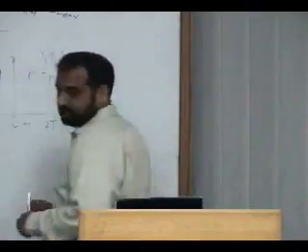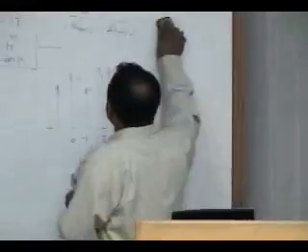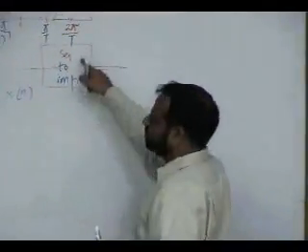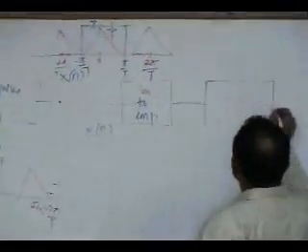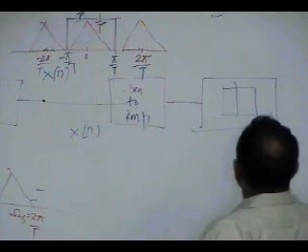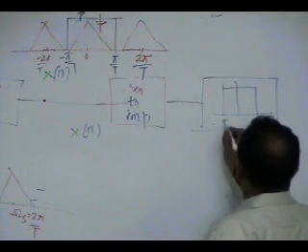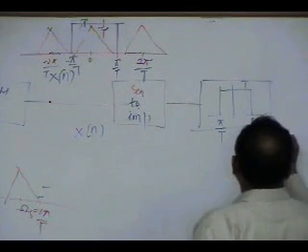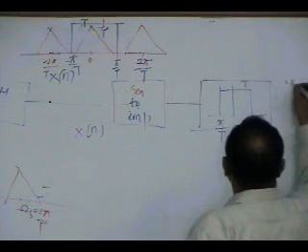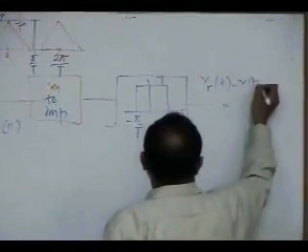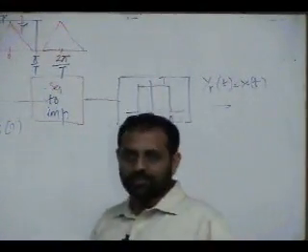Here we are saying, while going back from discrete to continuous, you first convert sequence to impulse, then pass your signal to a low pass filter with cutoff frequency pi by T, gain T, and this will return you the reconstructed x(t), which will be exactly equal to x(t), at least theoretically.